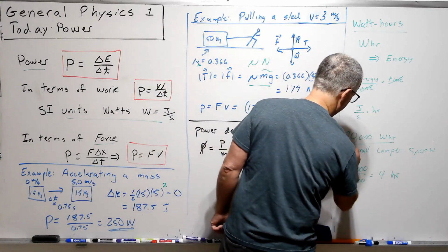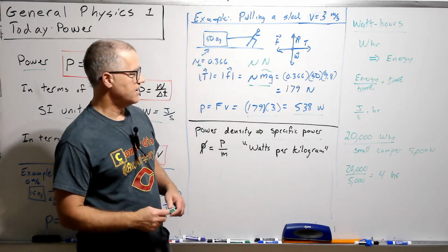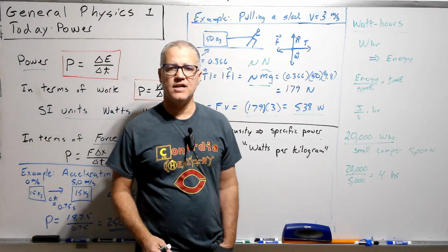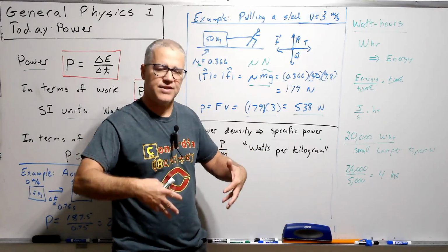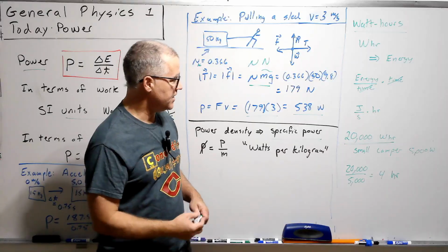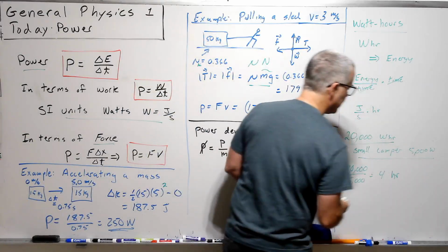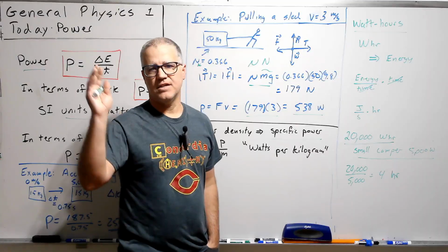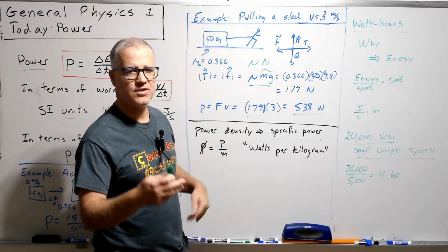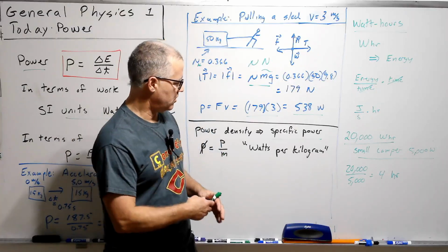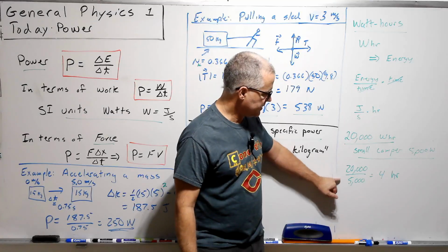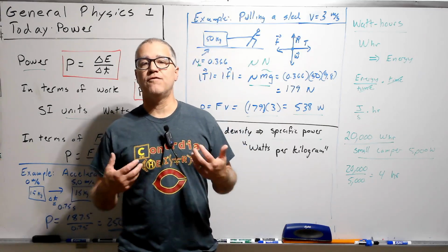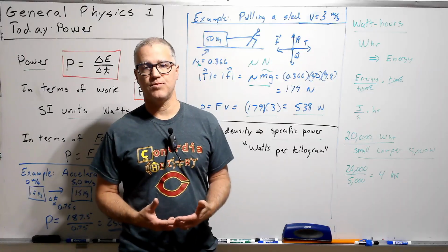So for example, let's say we had this battery pack that could supply 20,000 watt hours, that stored 20,000 watt hours of energy that it could deliver then as needed. And we're in a small camper that is consuming on average 5,000 watts during maybe the evening period of cooking and keeping stuff cold and all that. Then we could take 20,000 divided by 5,000, and we would get an estimate that you'd have about 4 hours of that kind of activity that you could do with this battery pack.